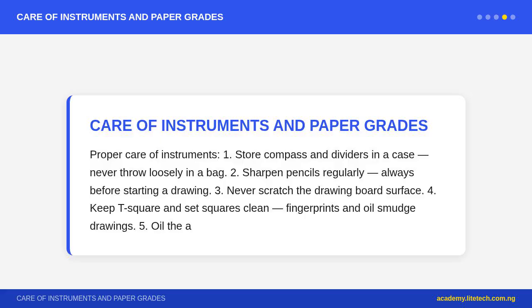Line types used in technical drawing. Continuous thick line, visible outlines. Continuous thin line, dimension lines, construction lines. Short dashes, thin, hidden or invisible edges. Long dash, short dash, thin, center lines, axis of symmetry. Long dash, 2 short dashes, cutting plane lines.